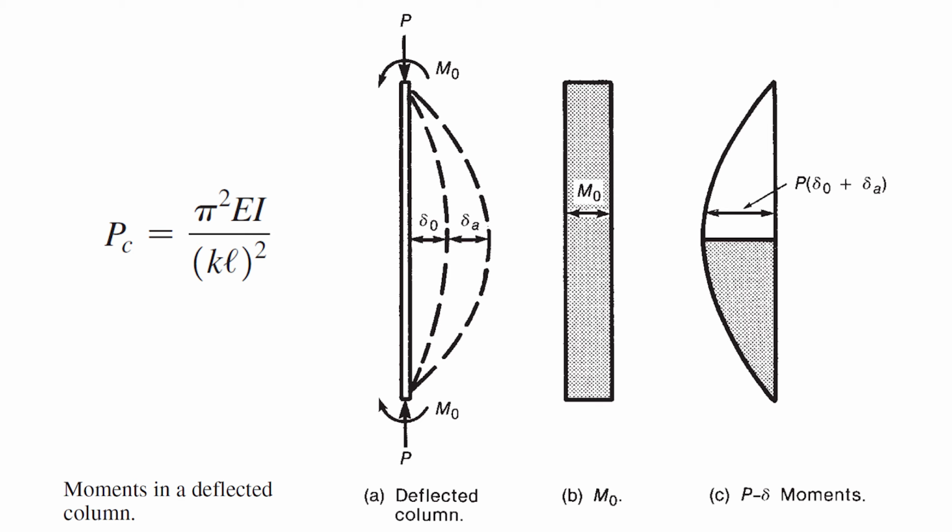The column section could be anything such as square, round, H, C, angle, any shape, as long as there is no local buckling. The final design formula for a concrete column or structural steel column according to the code of practice will look slightly different due to including the effect of the material behavior, such as cracking and creep in concrete or residual stress and initial imperfection in structural steel. Both concrete column and structural steel column designs are all based on this equation.